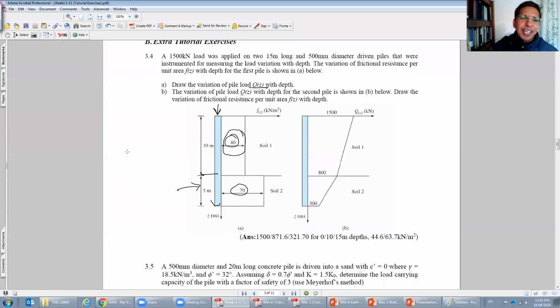So how do you calculate ultimate load for friction? Because this is friction, it should be clay. Okay. Oh, it can be sand. I don't know. But because friction is given, can I calculate now? What is the shaft friction, the shaft load? Q_s equals, what happens now? Let's do only the first layer. What is Q_s? Sum of what? The perimeter area, right? The area around the pile times what? Friction, isn't it? Yeah.